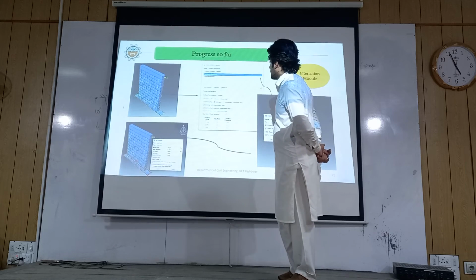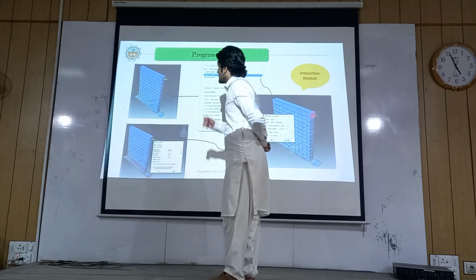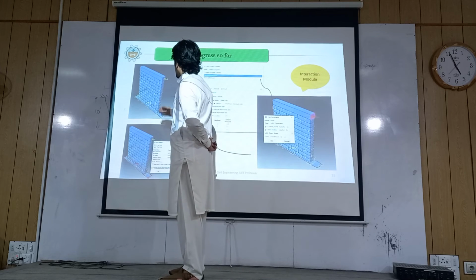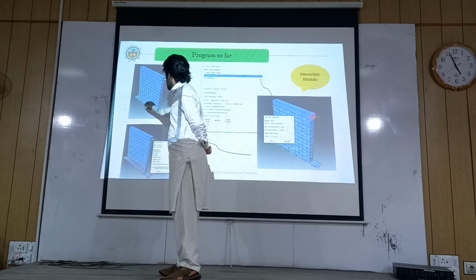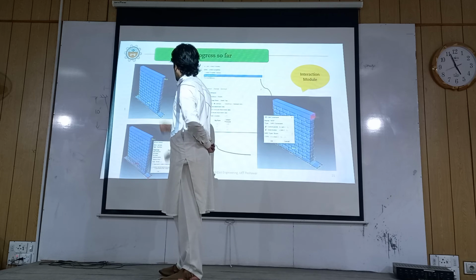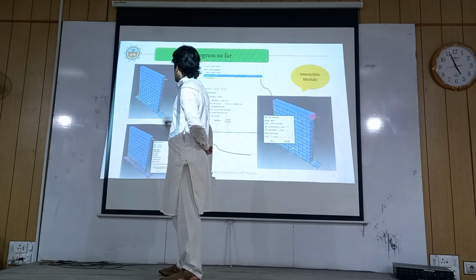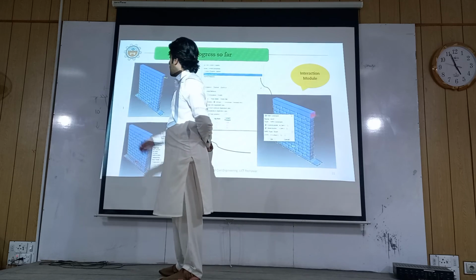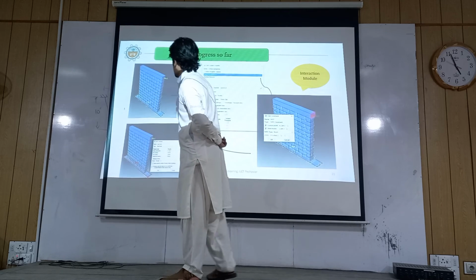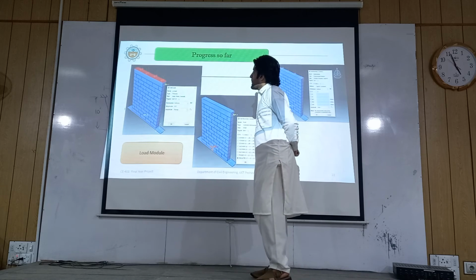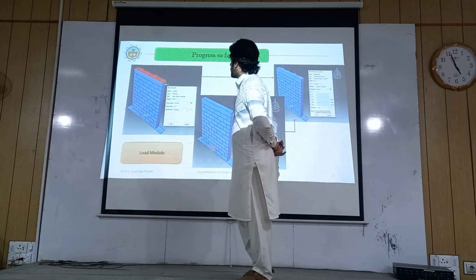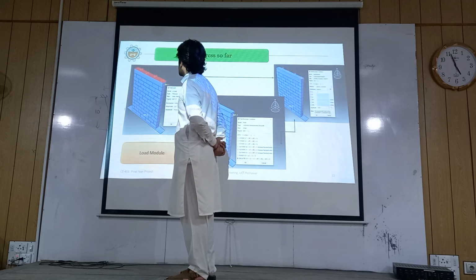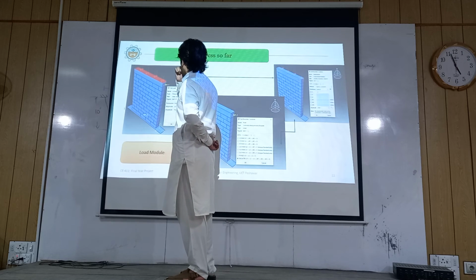These are the contact properties, in which the foundation plate is fixed. The foundation plate is fixed with reference point 2, and the bricks have been assigned tangential behavior and normal behavior. These are the loads, in which we have applied a pressure load of about 103 psi.